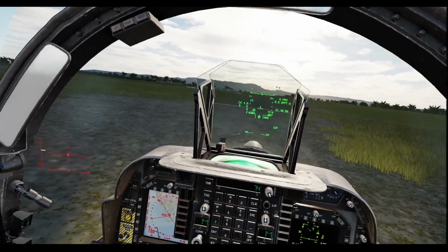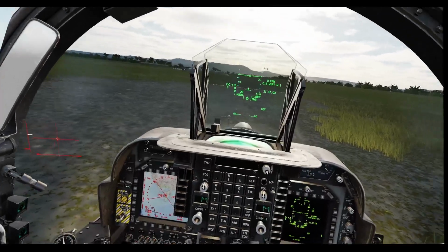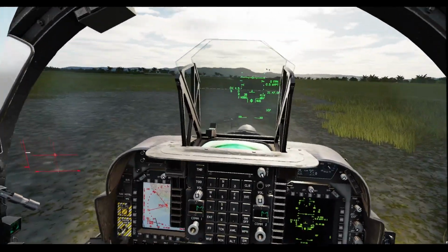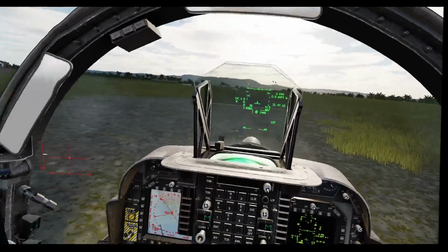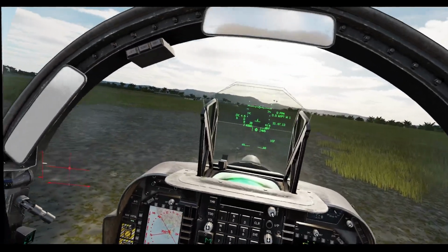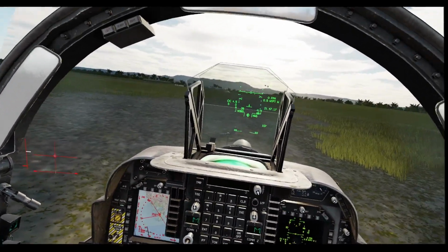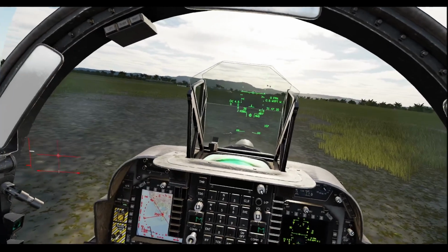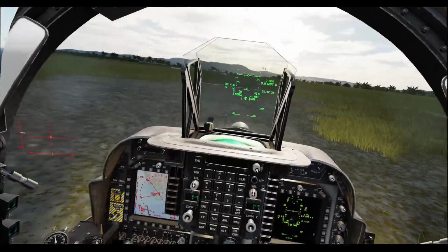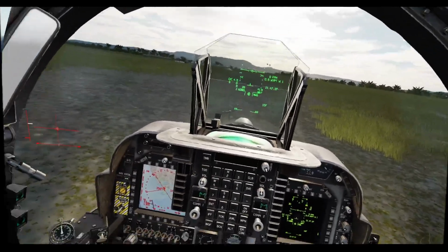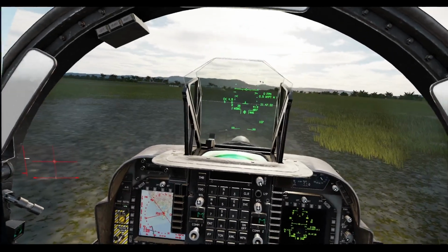Remember that if you bring the nose wheel steering on whilst you still have the rudder deflected, say the wind is to your right and you're pushing rudder right to counteract, you might find that you're pushing the rudder left to counteract the wind, because the wind is actually pushing the rudder at the back on the right hand side, so moving the nose right. And then as soon as you press the nose wheel steering button, you find that left input is quite drastic, and it bounces you off in the other direction. So just remember to get it under control before you activate the nose wheel steering.